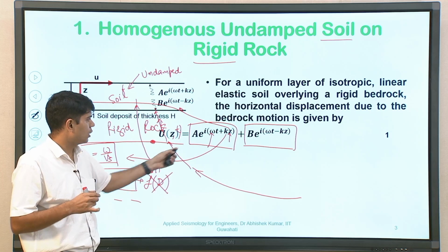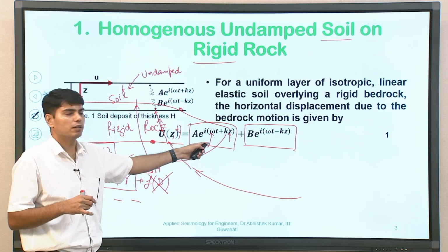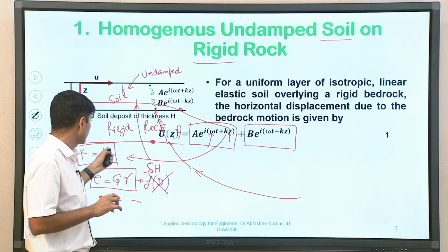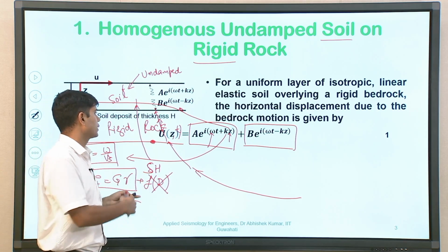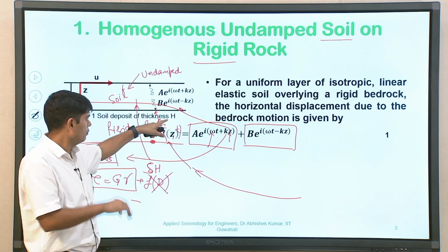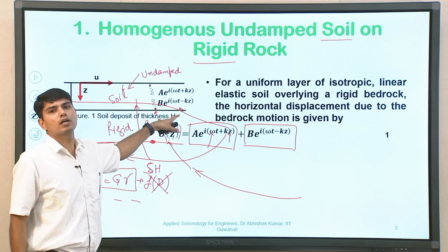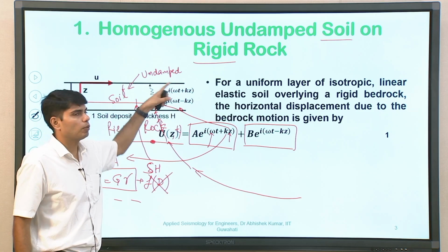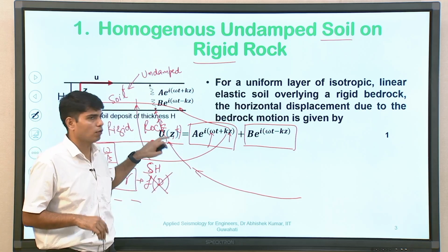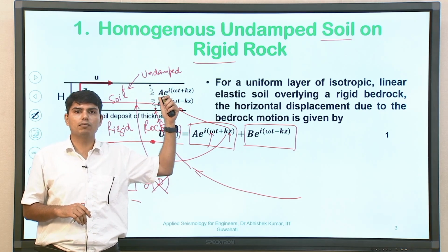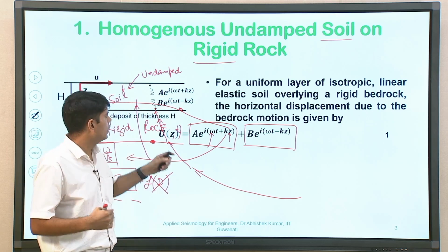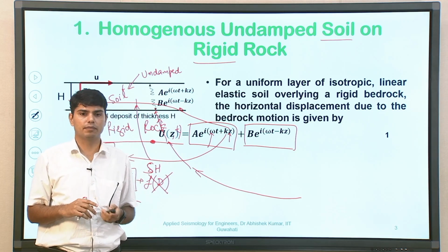So, taking that ground motion into account, and the medium characteristics which are defined by the k value, which is an important component correlating with the operating frequency and stiffness of the medium, we will try to find out how the motion which has been incident at bedrock level will be changed from the bottom of a given soil layer to the top of the soil layer. So, solution of the one dimensional wave equation means finding out the functional form of u. Solution of this particular problem is to find out how much the modified ground motion will be at the top of the given soil medium.